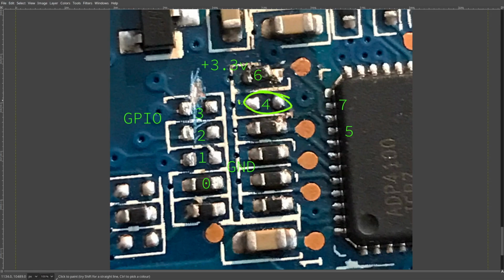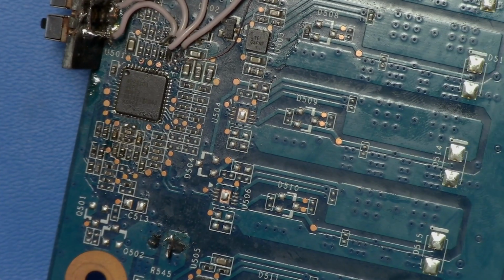VID 4 is connected just to ground, if I remember, well, to ground and then through to this via. So to disconnect VID 4, I had to cut the trace here, and that's what that kind of big mess is. I had to cut deep into the PCB, cut the trace completely, but I managed to do that, and it's all good. So this is actually not too hard to VID mod. As you can tell, this is the only real pain. So now I'll show on the actual card what the VID mod looks like.